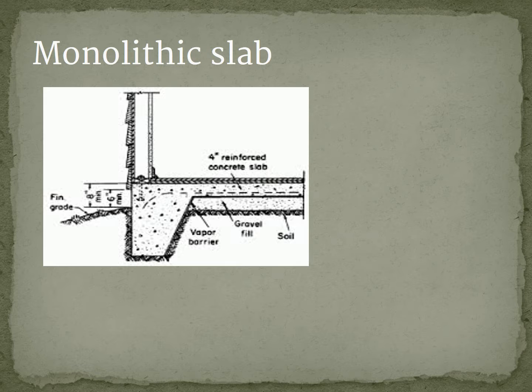As you can see also, there's no hollow block foundation. So obviously this is going to be important because you're going to use the 4 gallons per 10 linear feet on this house. So when you sell this job, you may add that in and say, hey, we're not going to use 10 gallons per 10 linear feet as we would on a supported or a floating slab because this is monolithic. So to me, this is your easiest type of home to treat because it is going to be less work. But keep in mind, the 4 gallons per 10 linear feet is going to cover everything you need.